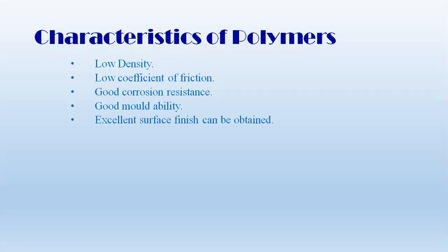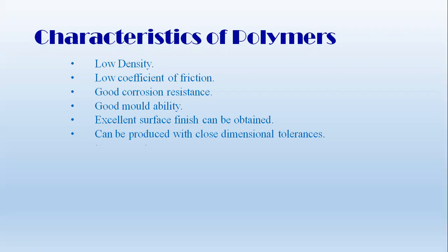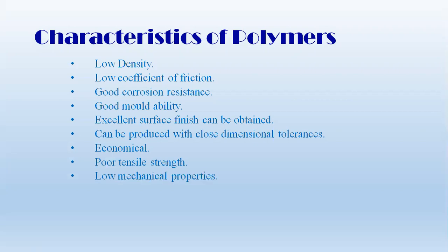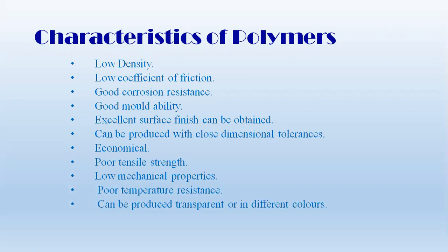Excellent surface finish can be obtained. Can be produced with close dimensional tolerances. Economical. Poor tensile strength, low mechanical properties. Poor temperature resistance. Can be produced transparent or in different colors.